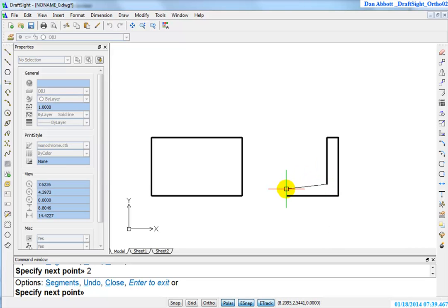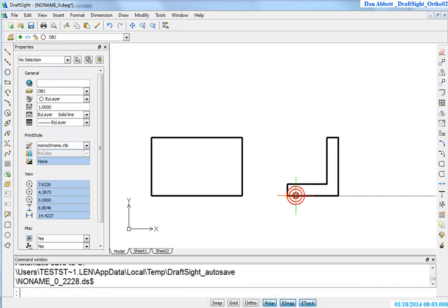I'm going to go over and hover over this end now, come back up, 2 more tracking lines. If they're visible, a left click goes to the intersection. Now I can go all the way down here, select endpoint. You notice I'm not going directly to the endpoint of the line, I'm going over here just to make sure that it really does go to the endpoint. If I'm too far to the right, I'm closer to the midpoint. Go left a little bit, I'm closer to the endpoint, left click, and it closes up.